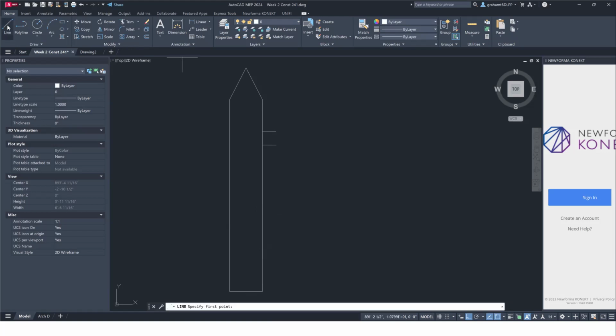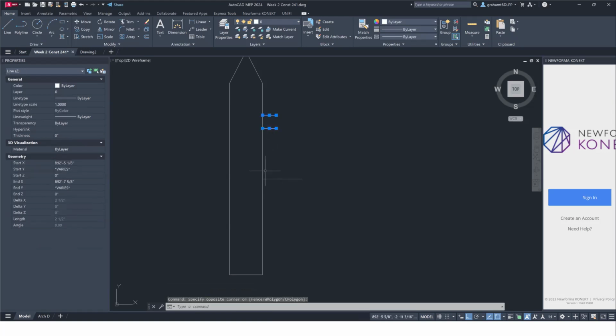So we're going to utilize the mirror tool. Okay. And in order to utilize the mirror tool, we need to draw one more line, and that's going to be a midpoint right here. So drawing a line off the midpoint of the right-hand side now gives me a place that I can mirror from. So what that means is I'm going to take these two lines, and when I mirror, it gives you two options. It actually is kind of like copying and moving at the same time and mirroring. I'm going to type in mirror in my command, or I can click this mirror command up here.